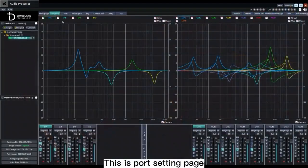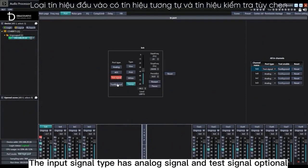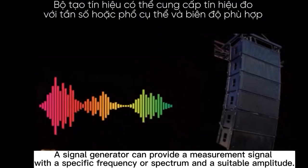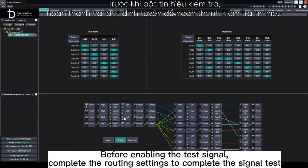Port setting. This is port setting page. There are input port setting and output port setting. The input signal type has analog signal and test signal optional. A signal generator can provide a measurement signal with a specific frequency or spectrum and a suitable amplitude. Before enabling the test signal, complete the routing settings to complete the signal test.